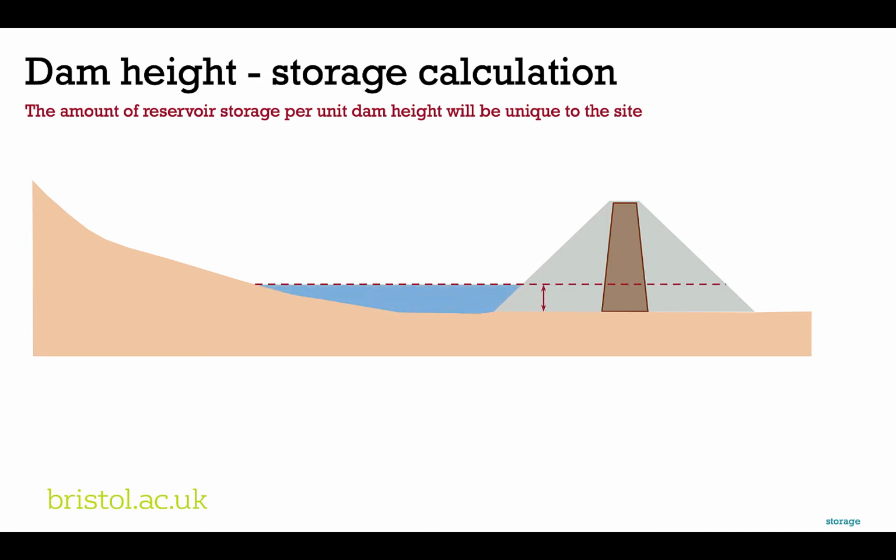You need to have a minimum water level behind your dam, and this is there in order to provide some allowance for sedimentation of the reservoir, but this is also to provide some constant head of water available to provide your compensation flow. This is specified for your project as being 5 meters of dam height, and the storage that is provided behind that is known as dead storage, because that is the minimum water level that is allowed, and there's no way to change that.